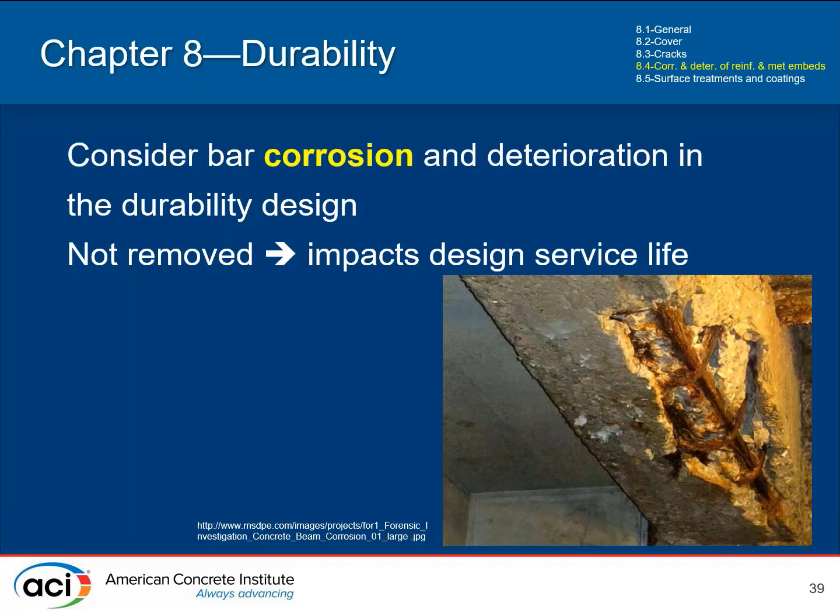However, what the code does talk about that I do want to highlight first is that you need to consider what the corrosion has done and how it will affect your design service life as well as other performance requirements. So it doesn't mandate that you need to remove all the corrosion product from the steel, though there's a strong bias towards it, but it realizes that there may be situations where it is not technically or physically feasible to remove all the corrosion.